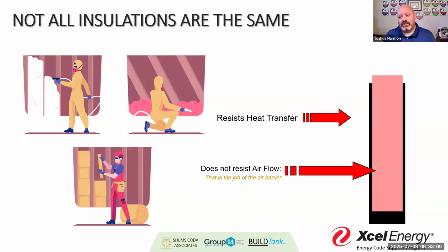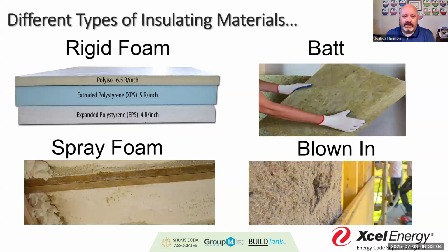They have different methods of installation, different thermal resistance values, but more importantly, there are different types of insulation that provide different qualities, right? So are we replacing what was originally intended as 3 inches of rigid insulation, which incorporated a water resistive and air resistive barrier, with a batt insulation, right? So again, there are going to be modifications that I think are important, and we'll talk more about those as we go throughout the plan review series.